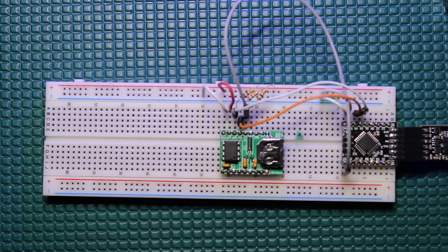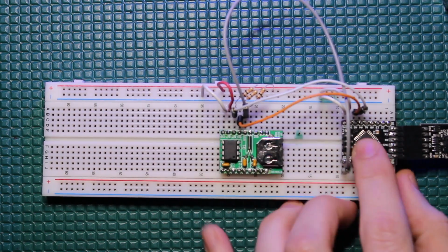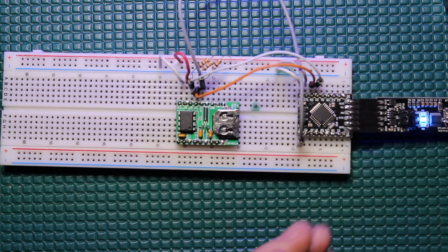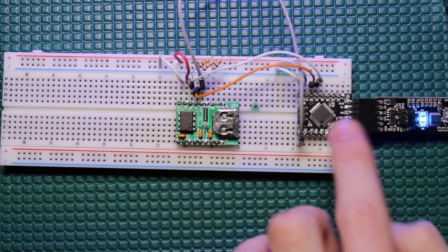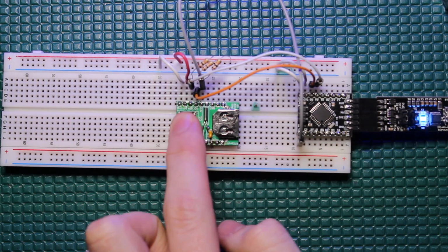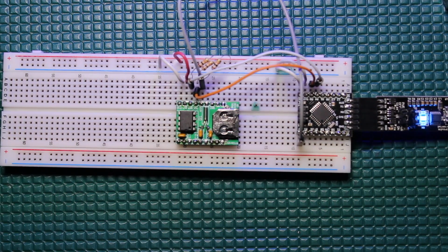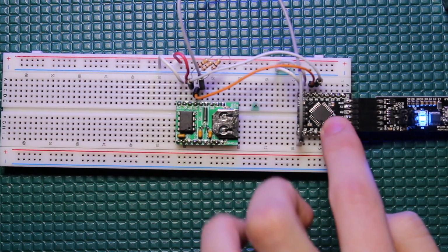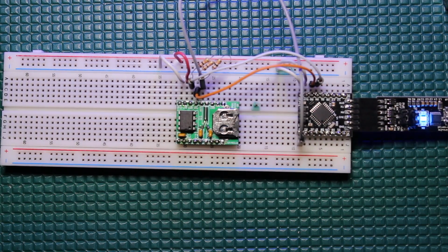very useful is low power wake up. So like over here on the Arduino, if you wanted to sleep this in an ultra low power deep sleep state where you only wake up from an interrupt, you can actually communicate over to the RTC, configure its alarm to wake you up in 5 minutes, and it will do that. And then you can go to sleep. It'll then wake up in 5 minutes and trigger that alarm. You wake up and then do whatever you had to do.